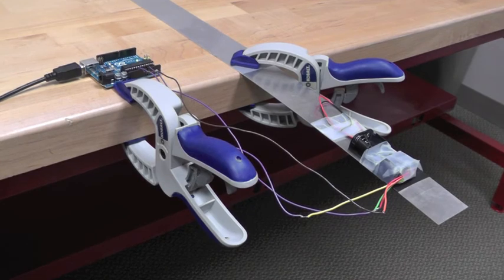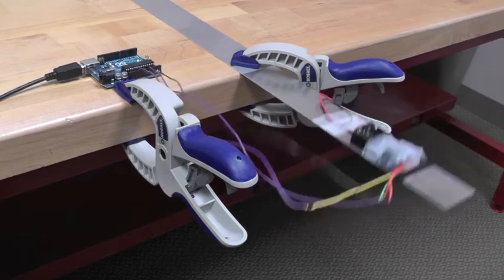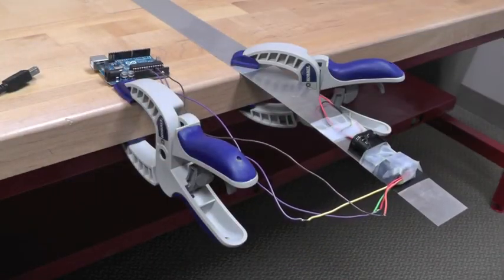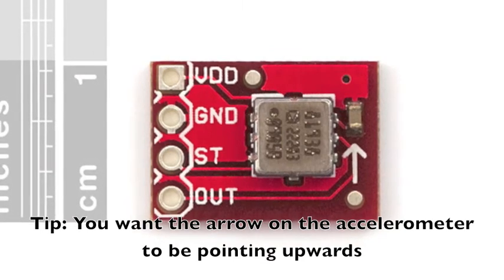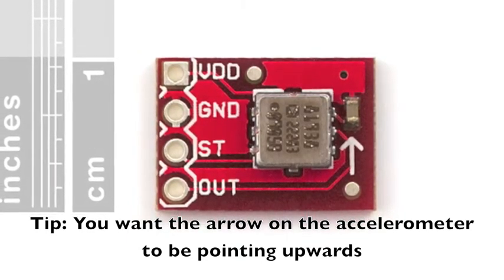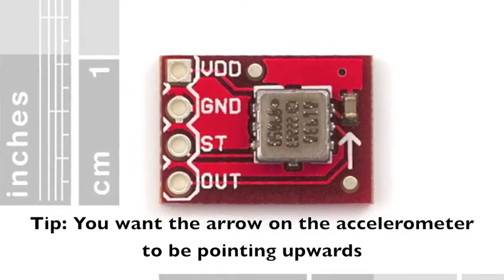To run the experiment, once the accelerometer is attached to the metal arm and the code has been uploaded to the Arduino, simply depress the metal arm and release. Once the metal arm stops oscillating, you can disconnect the Arduino to stop data recording. The breakout board of the accelerometer should be mounted perpendicular to the metal arm. This may require using a separate piece to mount it vertically. You can use clamps or a heavy object to secure the metal arm to a table.